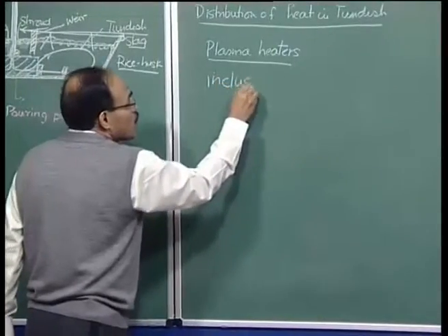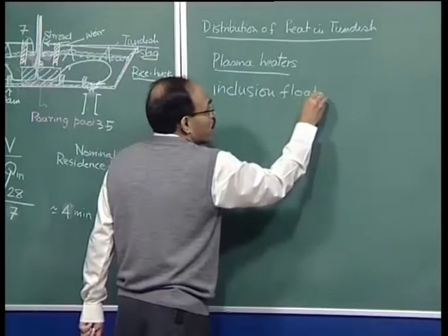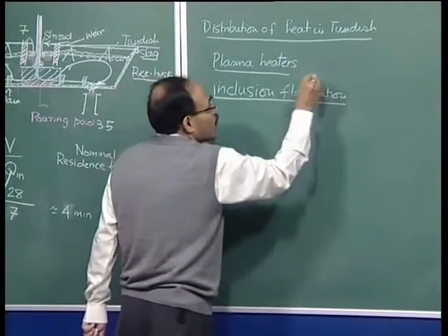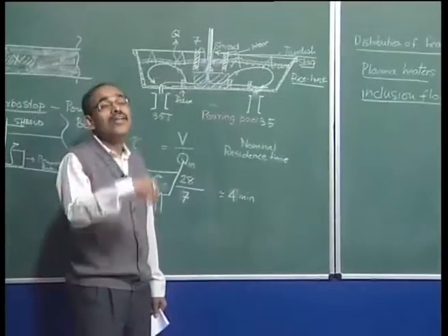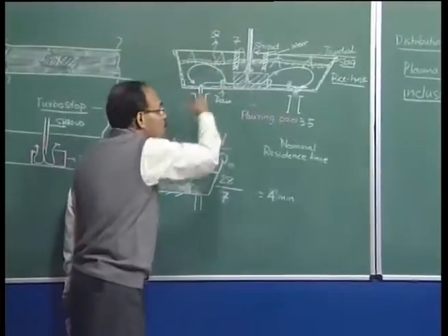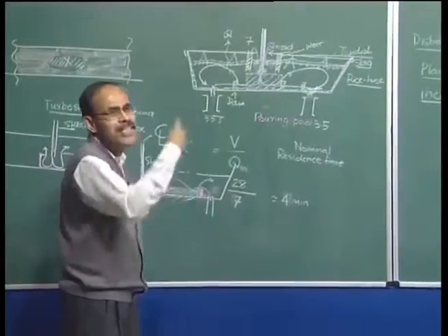So, we learn from this that the fluid flow conditions which are conducive to inclusion flotation are not the same as the conditions which are required to enhance the temperature of molten steel. So, for enhancement of temperature or of material mixing, if you are adding some alloying additions to distribute in the system itself, we will require a high velocity, high mixing conditions.